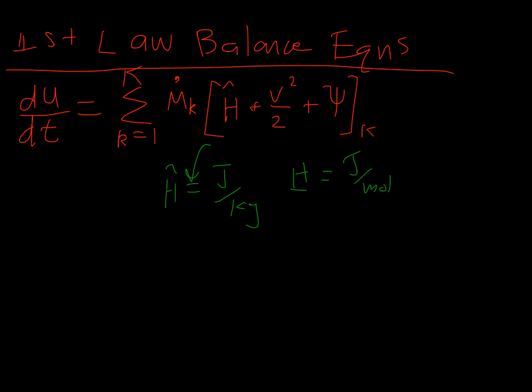So for every stream coming in, the mass brings with it enthalpy in the form of chemical bonds, bond vibrations, molecular motion. It brings with it its kinetic energy in terms of the bulk fluid flow. Now that's not the molecular fluid motion; that's going to be the enthalpy. And also any potential energy that comes with the system. In general, we are going to neglect the kinetic energy and potential energy. It's much, much smaller than the enthalpy.